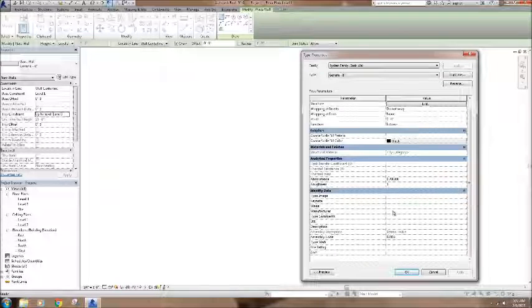So you probably don't usually have a manufacturer that you want to put in for an entire wall assembly. You might have one for a material specifically, but depending on how you want to build your model, you might just associate a manufacturer with a wall type, and that manufacturer just corresponds to the exterior cladding or something like that. You can do it that way.